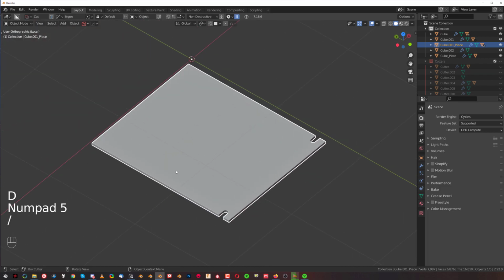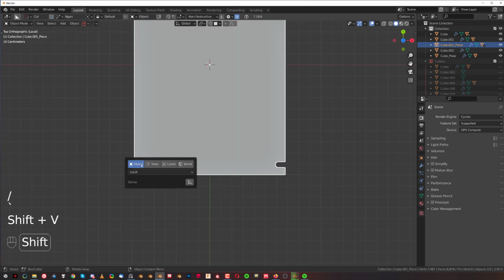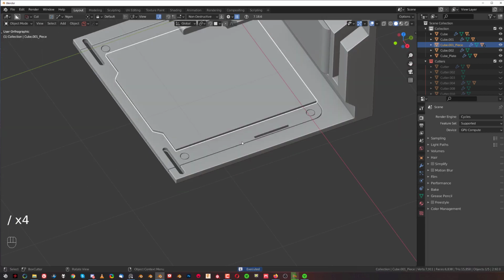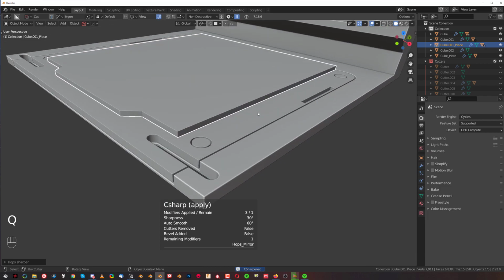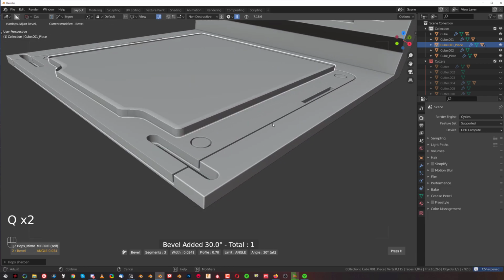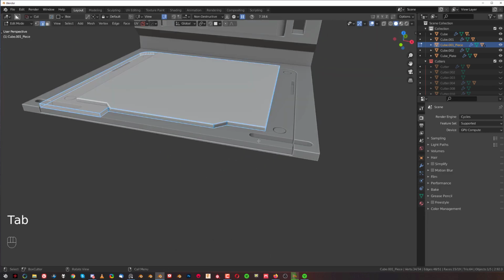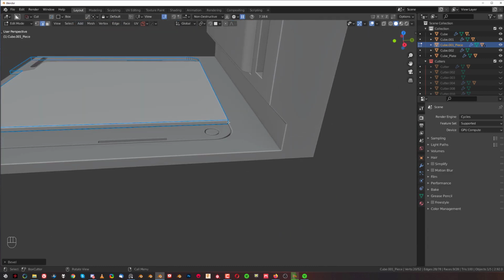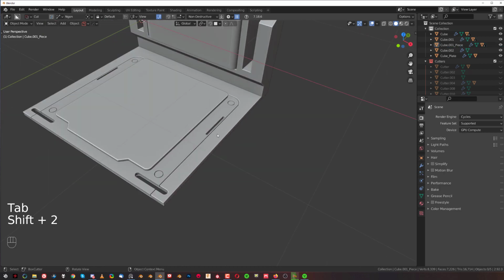So end gun, let's go to local, go to top view, Shift V and view mode, and slice it here like that. Actually from the other side, because we got mirror from the other side, right? So from here, come on, there we go, that's better. How are we looking? Yeah, we're looking pretty cool. Sharpen this, and let's bevel this, give it a thicker bevel, okay, but don't overdo it. We could select this corner and bevel the corner here, and bevel the corner here, and peachy. So that's that.